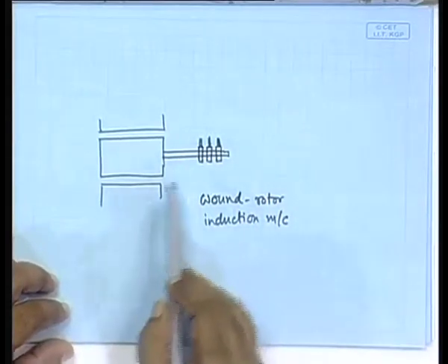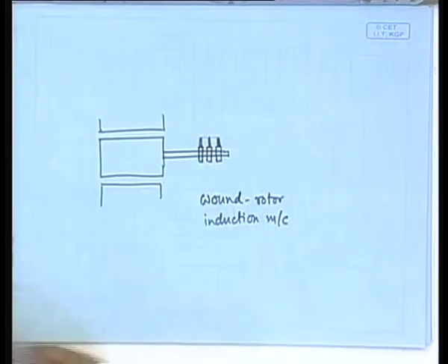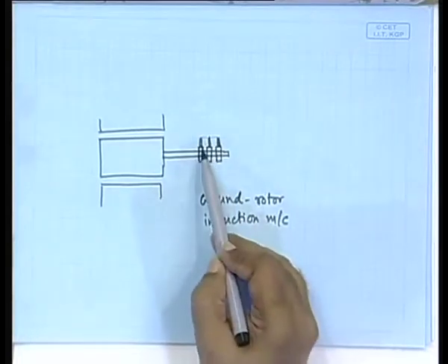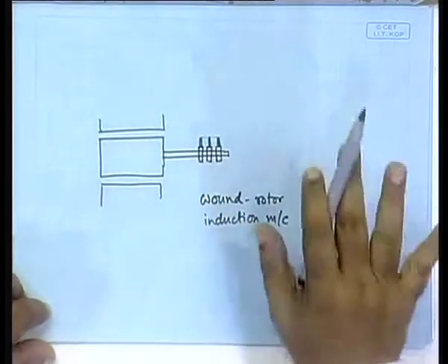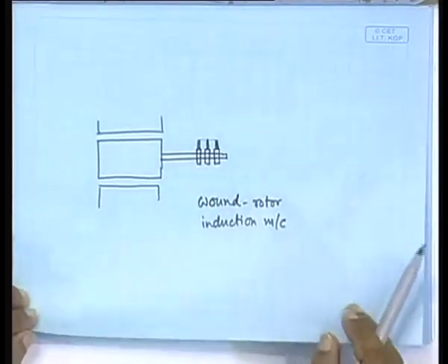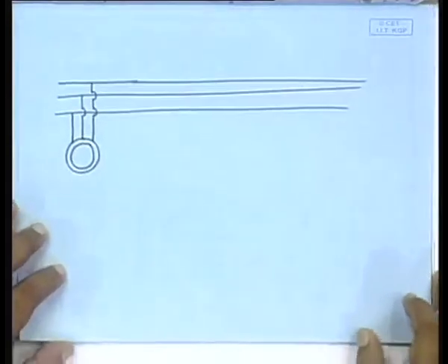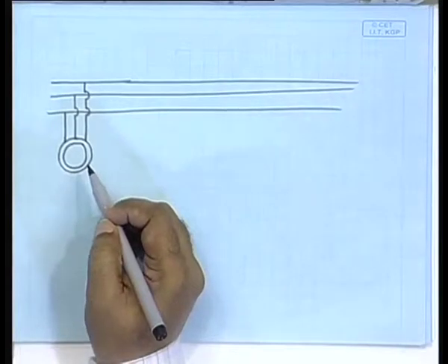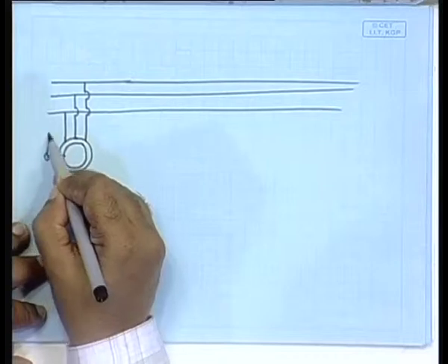But in that case, normally this terminus will be shorted. Why? Because you need the rotor to be shorted. But notice that you still have the option of connecting something there. For other reasons, this is used right now in industry, but this can come in very handy for our purpose. So, imagine that this is physically connected to our wind turbine.